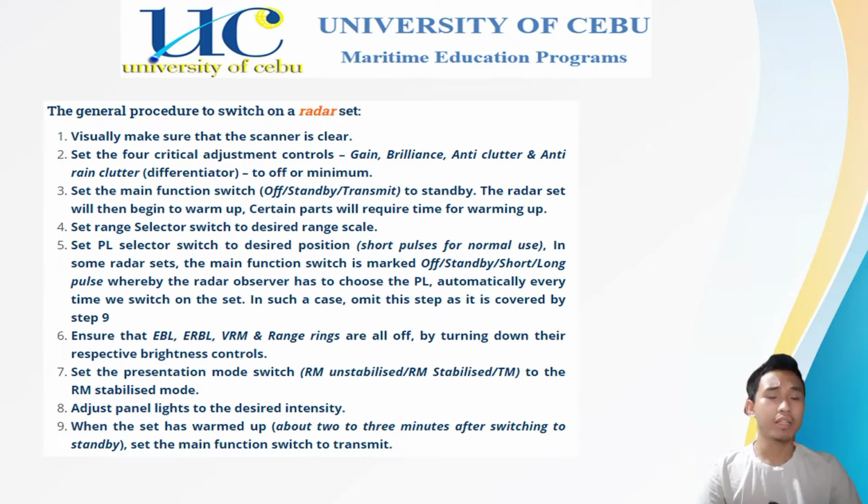if rain or sea clutter is set too low, it is highly possible the targets will be hidden in the clutter, whereas if it is set too high, it will cause targets to disappear from the radar screen. The radar can also detect rain, snow, or hail clutter in the same manner as normal targets.